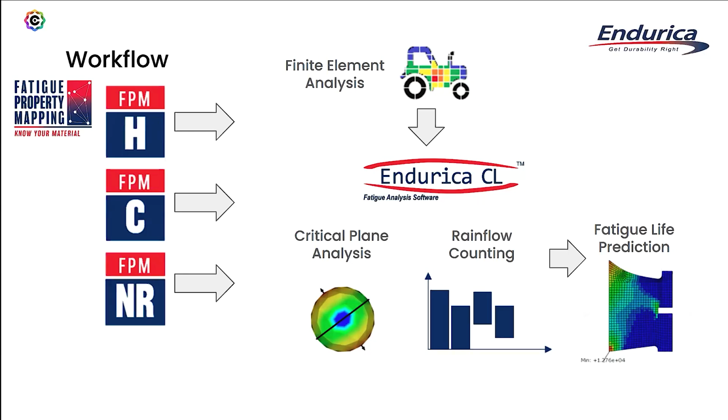The hyperelastic getting your stress strain curves, and core getting your basic fatigue models. And then depending on your application and budget, what's important to your project that you're working on, you might choose to include, say, softening or strain crystallization. There's an aging module. There's a self-heating, just to name a few of them. But there's really a full suite of materials that you can pick from.